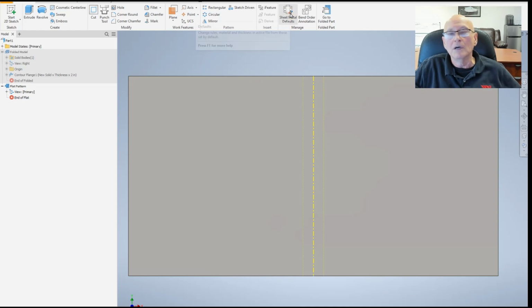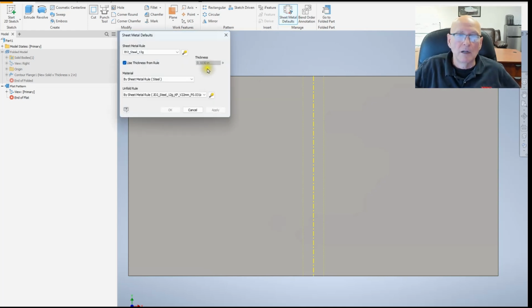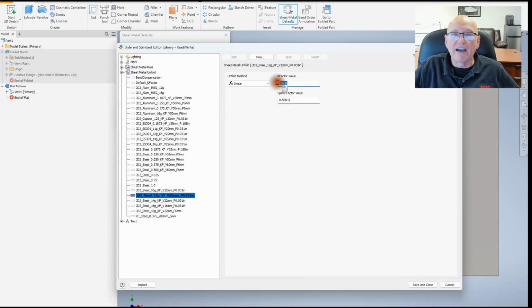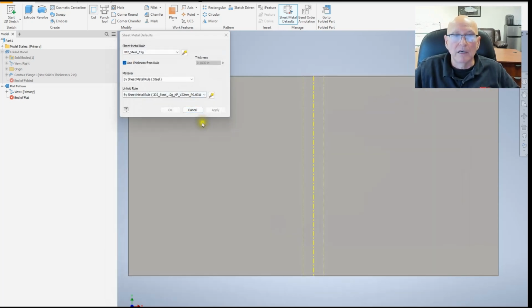So what we would do is go back to our sheet metal, and you're going to love this, we are going to change this K-factor to another number, go back, and check it again to see if it's at that calculated number. The 4 inches long minus the amount that we were too tall and too wide by. Adding those two numbers together, we're going to change that K-factor. Then we're going to go back over here. In fact, let me show you real quick. I think Inventor's going to let me do this without screwing things up too bad.